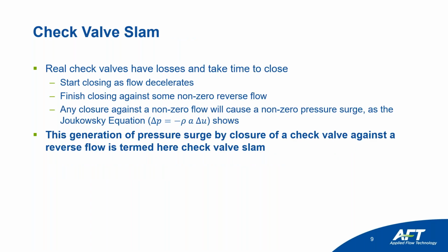Check valve slam. This is something that we've termed, and other people term, the closure of a check valve rapidly against a non-zero reverse flow. So this is not necessarily referring to the check valve face slamming into the check valve seat.